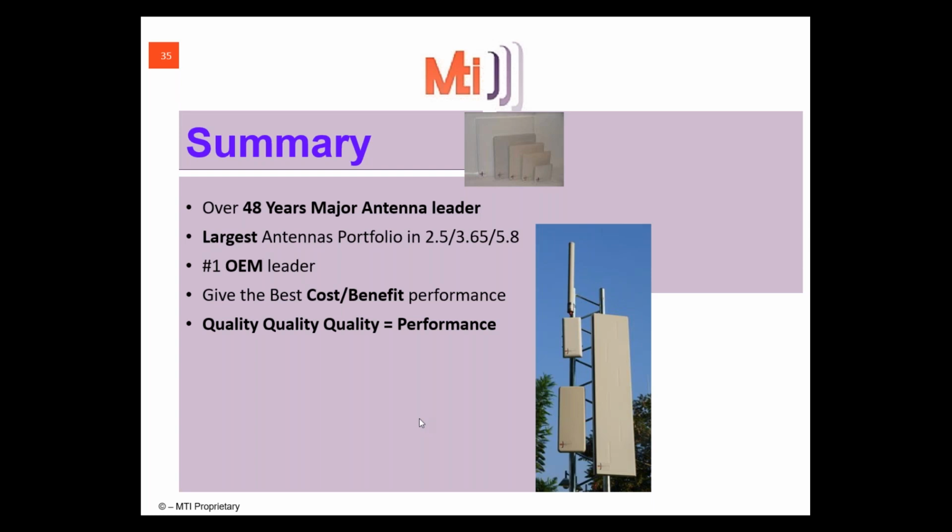In general there is no problem because the enclosure and the antenna and everything give you IP67. It's proof. The only issue that might be a problem, and this is our recommendation based on real market cases, is if you open the antenna after, I don't know, 6 months, 1 year, 2 years, for maintenance or to change something in the enclosure, we suggest that you replace the gasket. That's all. You replace the gasket because the old gasket is not good enough now. Once you open it, try to understand it's rubber.